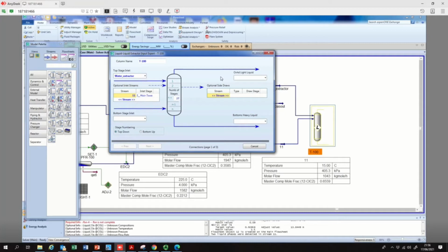So let's assume that we are going to perform 5 different stages. So we are going to perform liquid extraction, like 1 stage, 2 stage, 3, 4 and 5 different stages. Okay. So the number of stages should increase the purity. Based on the information from the industries, roughly 5 stages are more than enough to achieve a purified product. Anyway, we can check whether increasing the number of stages is increasing the purity of the material or not. So let's do that.